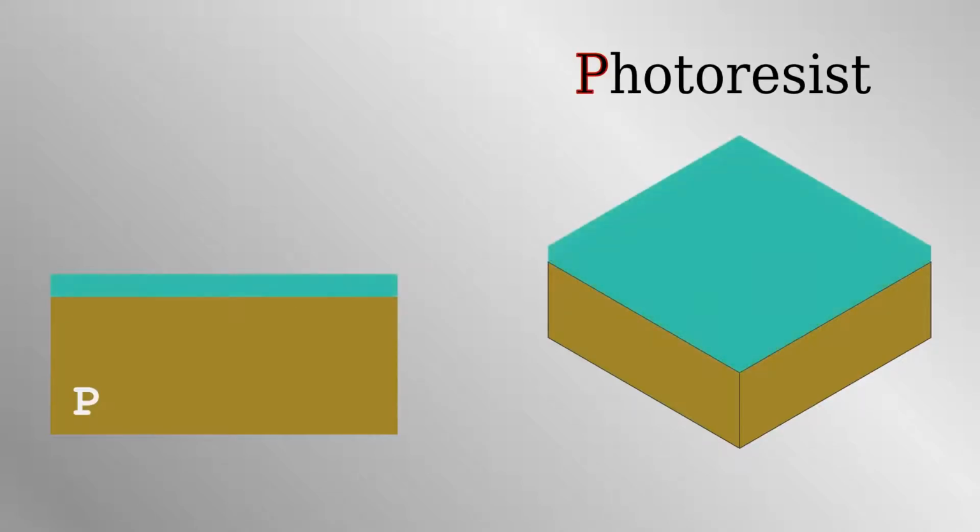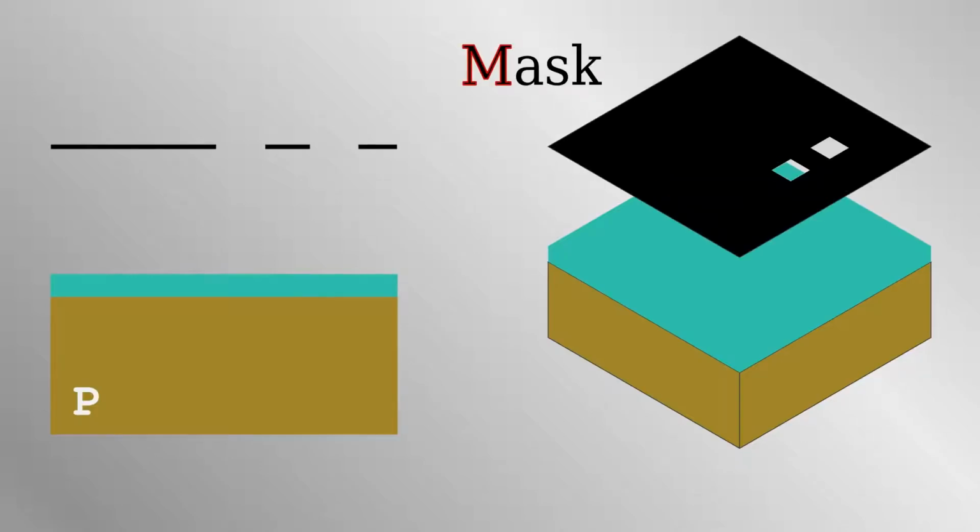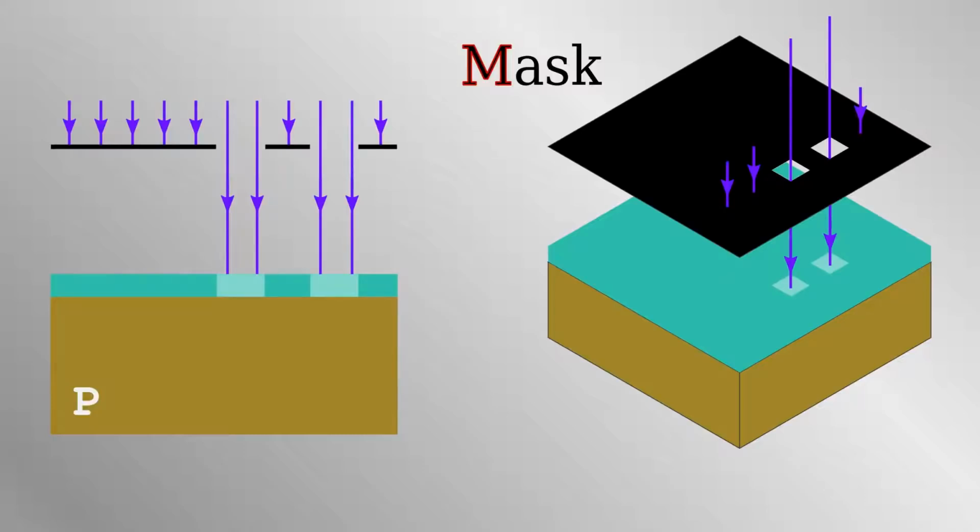Unwanted surface material is then removed by a second technique called etching. This is done by applying chemicals or hot plasma to the top of the die. Several steps are taken to ensure that the etching is targeted at specific areas, and therefore material is removed selectively. A chemical termed a photoresist is deposited onto the die. Light is shined through a mask, exposing predetermined areas of the photoresist.